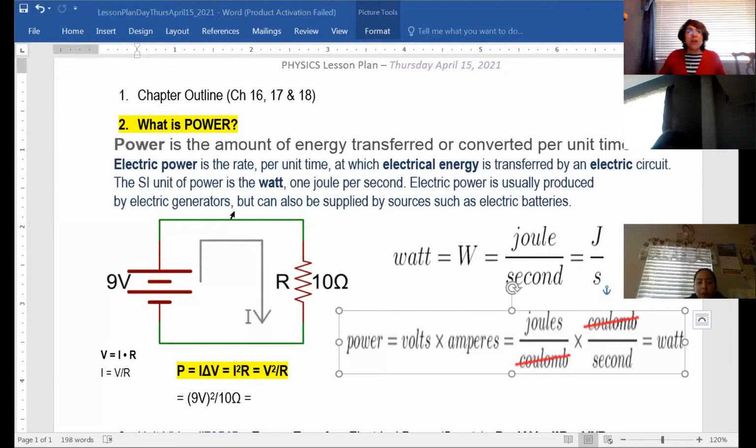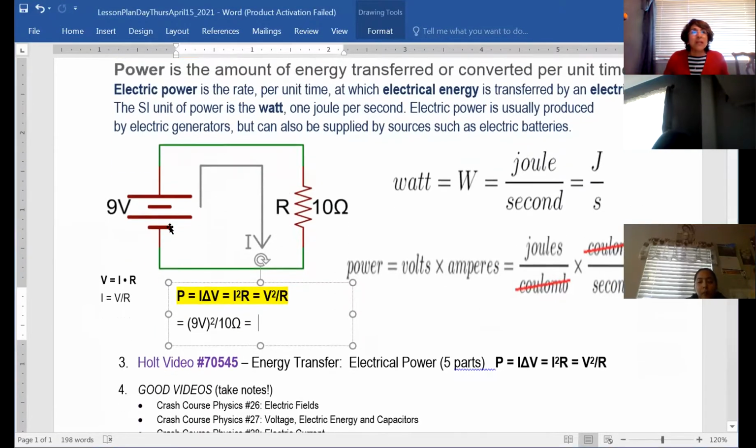Okay, so here's our first circuit of the day here. This one you can see. I wanted you guys to see there's different ways of representing the battery. For me, it's easier just to do the plus minus inside of a circle, but you do want to understand this one. So this one could be two batteries in series. The longer line means the positive terminal of your battery, and the shorter one is the negative terminal. So you might want to write a plus on this side here and a minus on this side here.